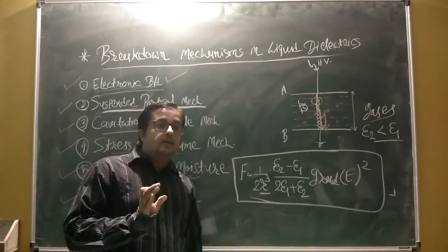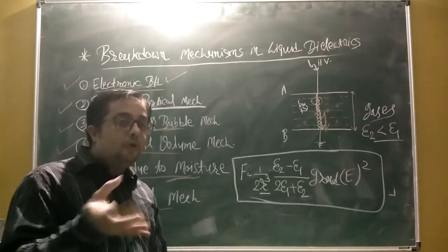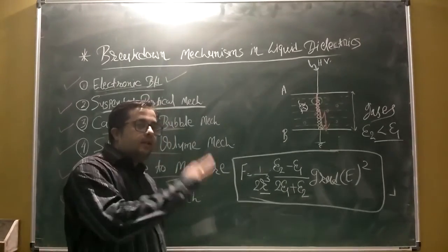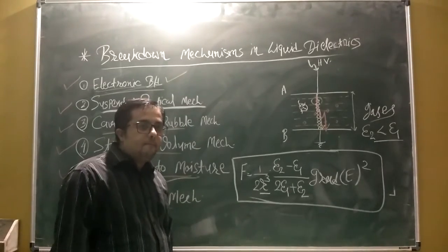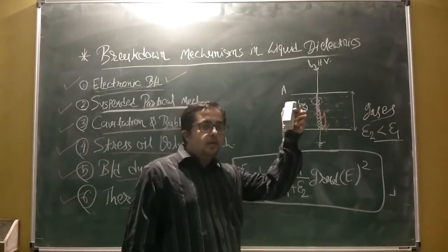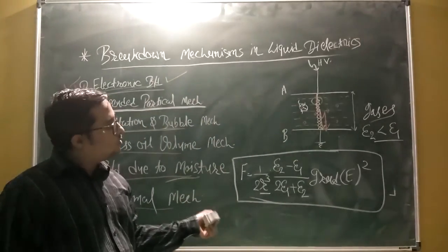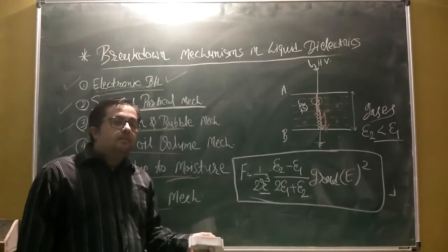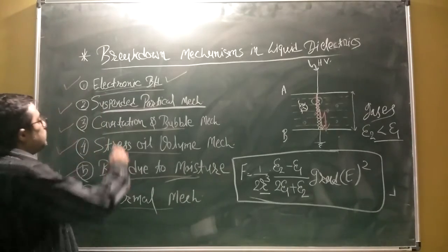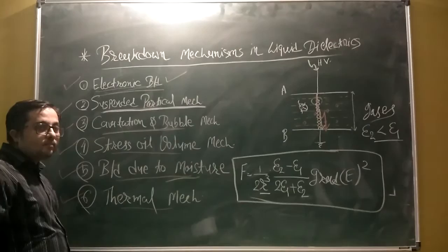Similarly, the particles are also suspended from their duty, and once they are suspended, they will emerge in the oil. Okay, but they are now dead particles, so now they are acting as a path for the conduction process. So this is how the breakdown will take place due to the suspended particles.